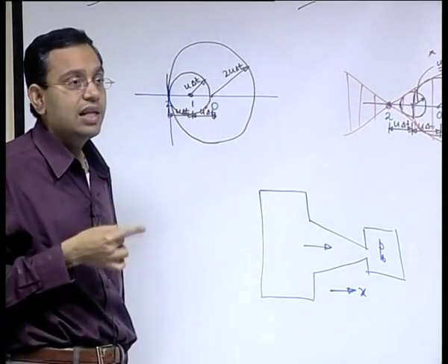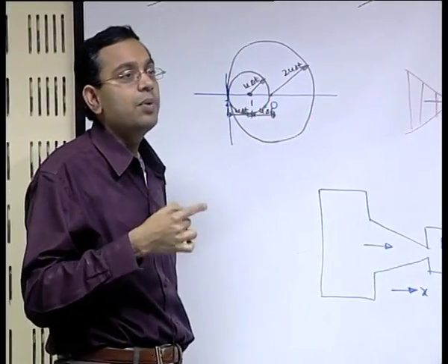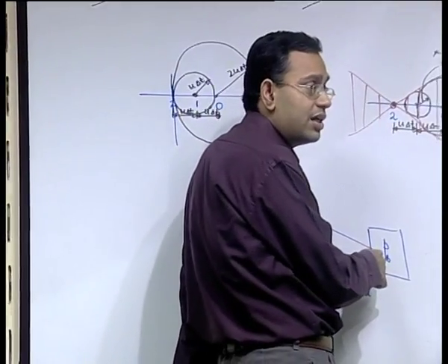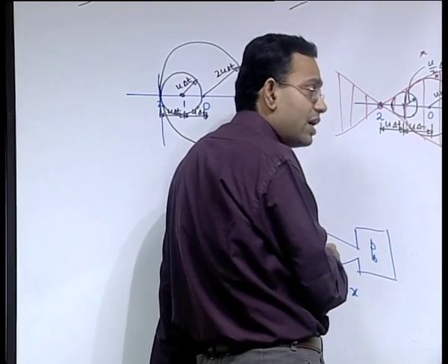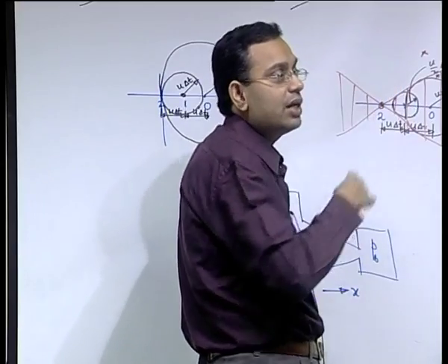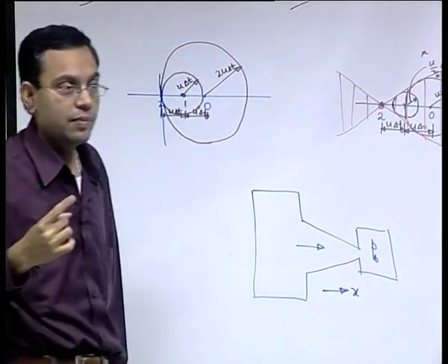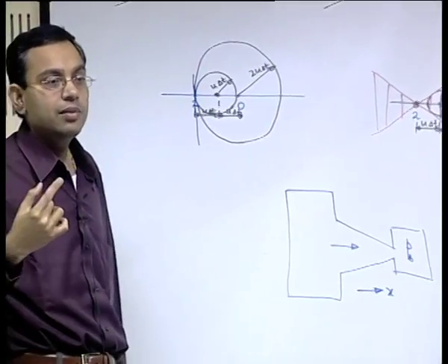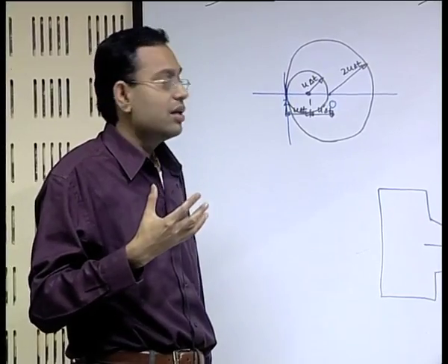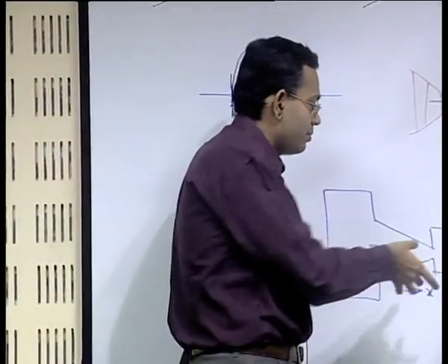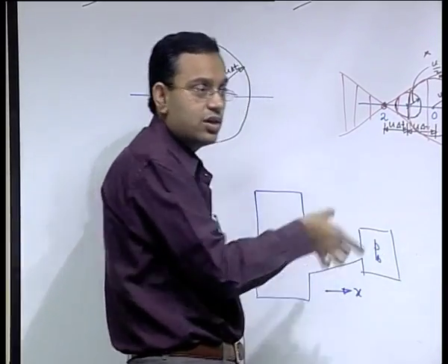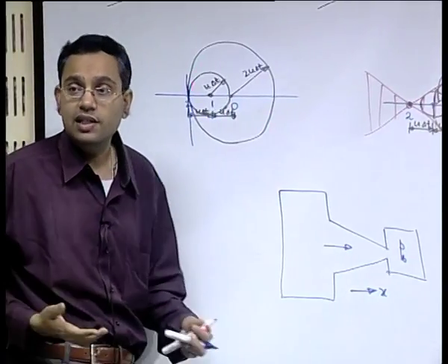But interestingly, that does not happen perpetually. So what happens is that if you reduce the back pressure, this mass flow rate increases, but it comes to a maximum when it reaches the sonic condition, that is, the Mach number becomes equal to 1, and then you cannot increase the mass flow rate further by reducing the back pressure. So this is a well known physics in compressible flow. Question is, why does it happen?